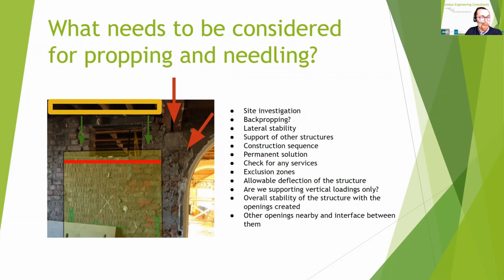And then the load directly above where we're going to put the lintel or beam is also separated because there's a surface riser duct opening through there as well. So these are the kind of things we need to look through. But now let's go through our list. Site investigation: we're looking for wall thicknesses, layout of the structure including floor spans and floor to ceiling heights, and floor construction. What is the floor made out of, and will it be suitable for point loading from the props when we go to prop, which leads us to back propping.